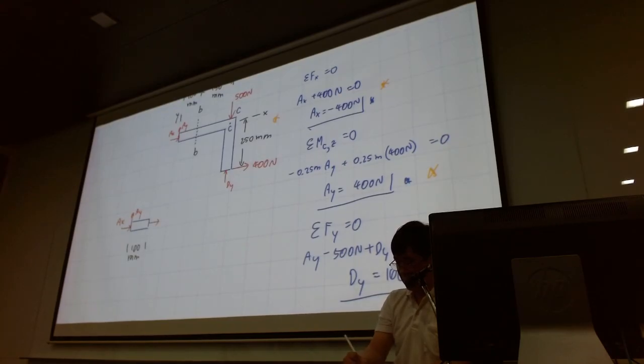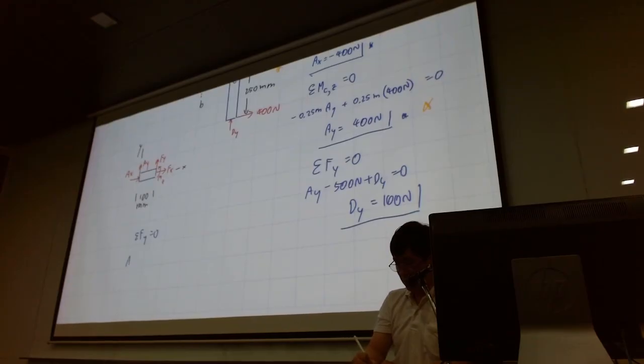Again, this is going to be my fx, fy, and m in the z, x, y axis. And from here, summation of the force in the y equal to 0, ay plus fy equal to 0, so fy equal to minus 400 Newton.